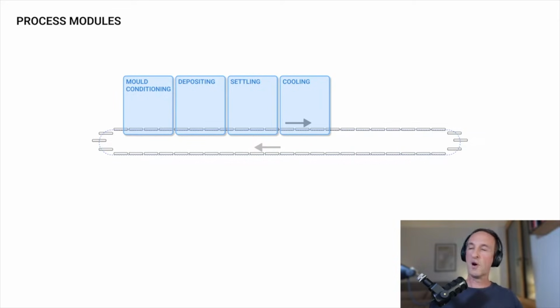After the cooling module, you could have an inspection zone. So an inspection module, this is where you check the quality of the product, the consistency of the product. Before they get packaged and distributed, you can have, for example, a vision system, or you can have, for example, a weighing station. Mettler Toledo, for example, makes weighing cells. So you can have a weighing station that checks for the correct weight of a chocolate bar, for example. So that's the inspection zone.